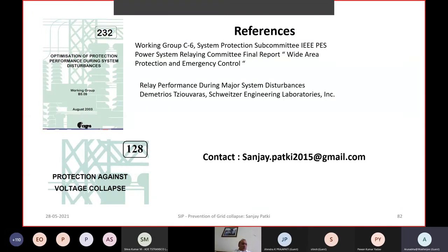No, in transformer protection, if there is a fault while the inrush phenomenon is there, the fault detection is a separate measurement, which is based on the fundamental current. Second harmonic blocking will not block in that case; it will directly execute the trip.